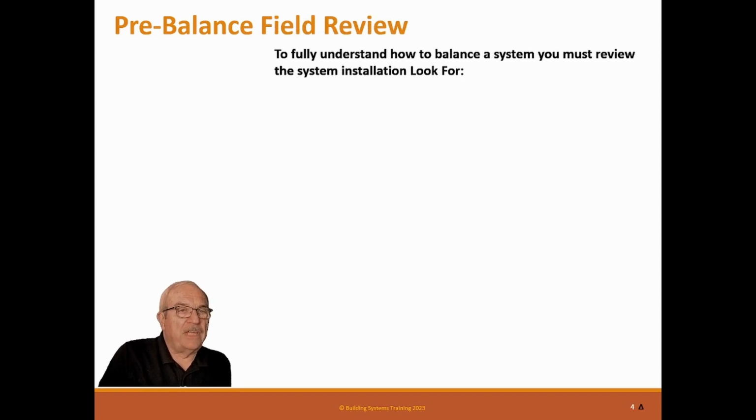To fully understand how to balance a system, you must review the system installation. So now you need to walk the site. And you should always walk the site before you start balancing. In my company, it was always our policy that the supervisor or the foreman would go out and walk the site with the technician before he started balance, because normally they weren't actually ready to balance.